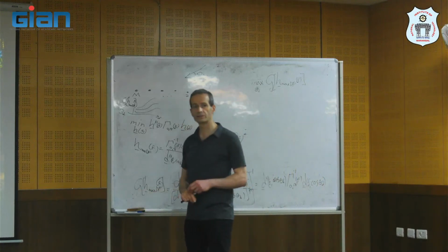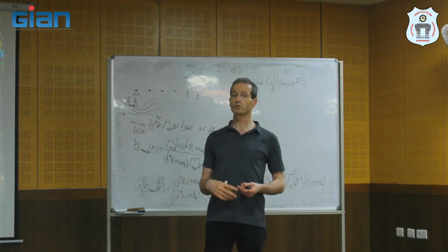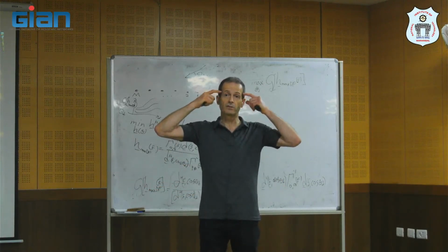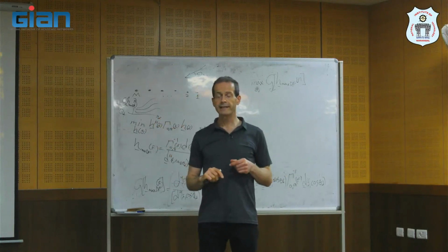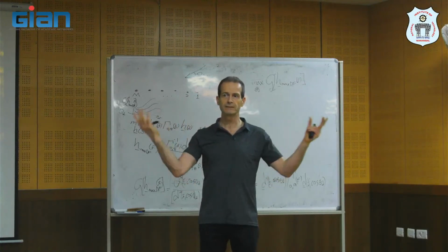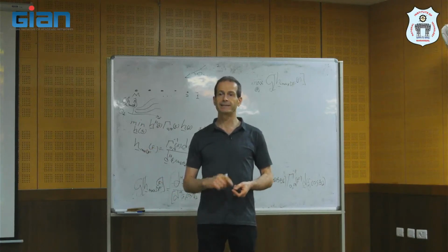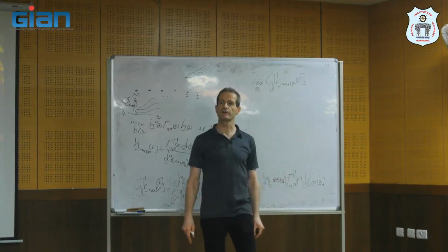Think about the smart glasses. Suppose that I want to maximize the directivity factor using an array of microphones on the frame. I want to design a fixed beamformer, assuming that the noise field is diffuse, and I design a beamformer that maximizes the directivity factor.